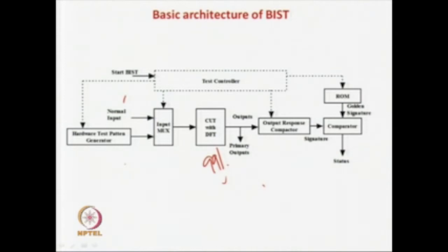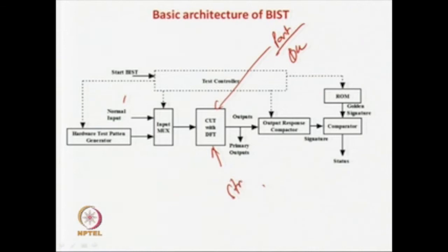So now this part is 99% of the area, which we will see later. This part of the chip is tested and verified, fine, and it is sold in the market after offline testing. Now it can happen that every time you start your operation, it may have some faults, or it may have some faults which develop when the circuit is operated. As all these circuits are fabricated in chips, on the board, it is very difficult to debug where there is a problem.